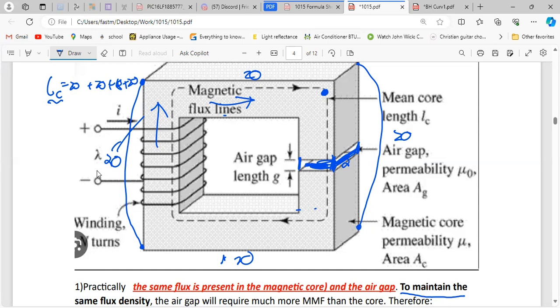So when you're doing your lengths, reluctance or whatever it may be, just remember if you have multiple air gaps, like if you have 5 air gaps, and you want the length of the core, you have to subtract all those lengths from the LC. Let's remember that.